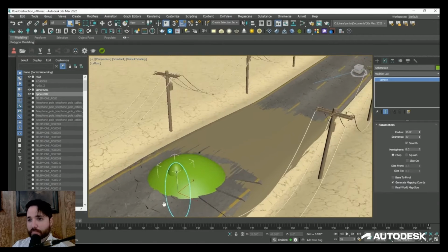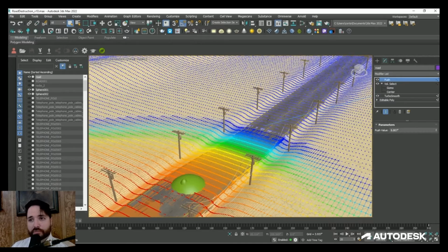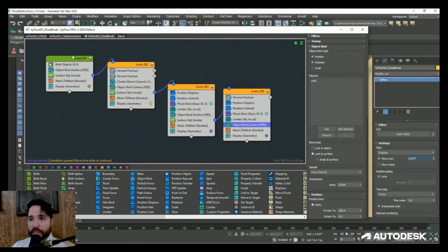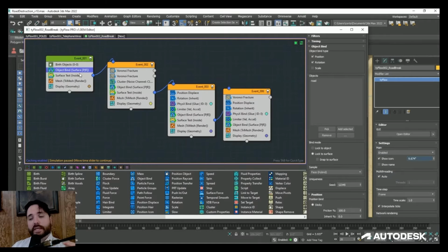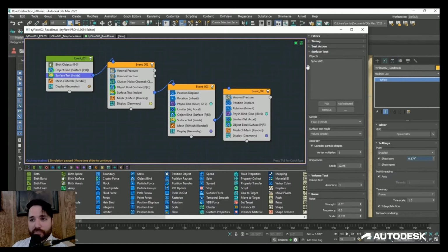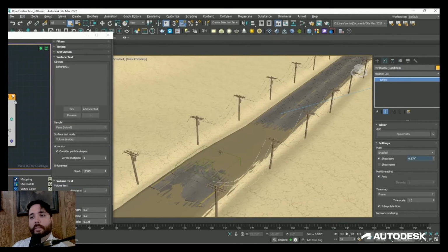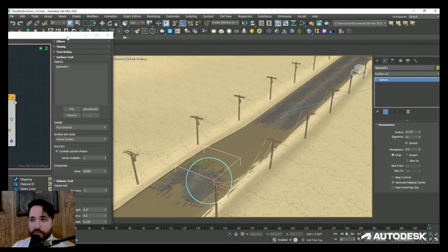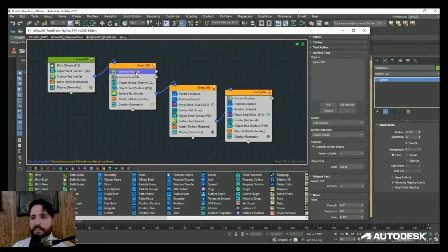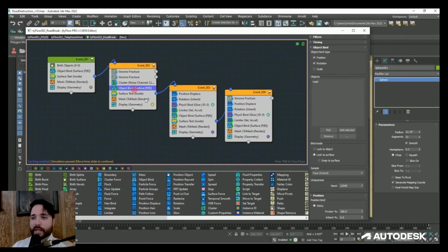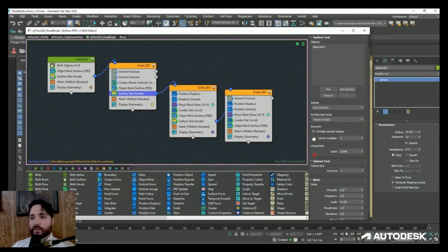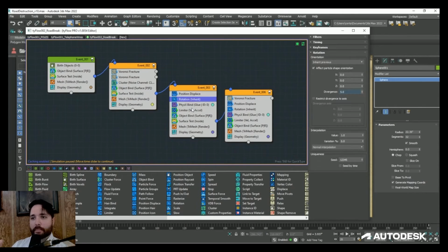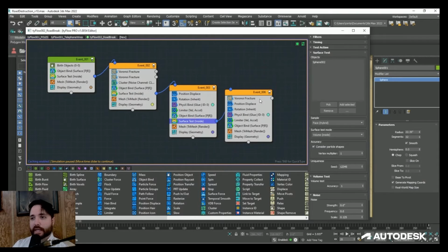So once that was set up, I was ready to move into simulating the various parts of my scene. Jumping into the first TyFlow simulation for the road fractures, I birthed the road into the sim, and I bound it to the desert mesh underneath. To trigger the fracture events, I simply used a surface test operator to test for the distance to our main sphere collider. As soon as the road mesh comes within a certain threshold distance to the sphere, it passes to the next event to be fractured into smaller pieces. I made sure to continually add object bind operators to each event so that our desert mesh rippled across the landscape. The fractured road particles would actually still stick to that surface.